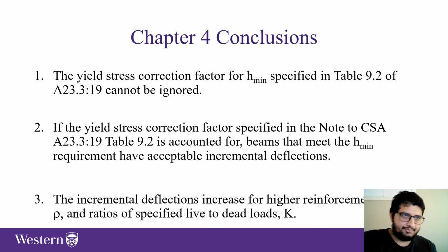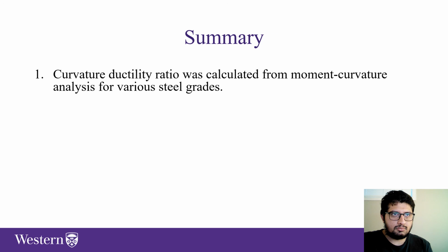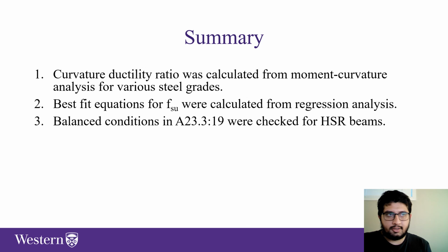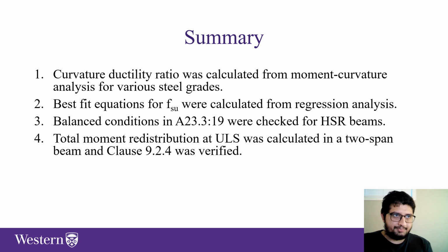Okay. So in summary, in chapter 2, we looked at the curvature ductility ratios, which are calculated from moment curvature analyses. And also the best fit equations were calculated from regression analysis. The balance conditions were also checked in beams reinforced with high strength steel.